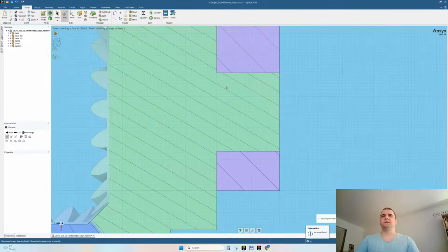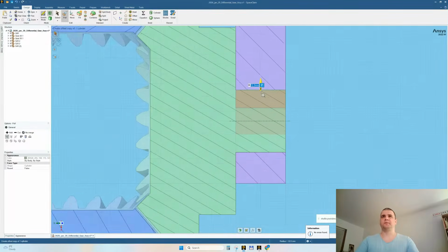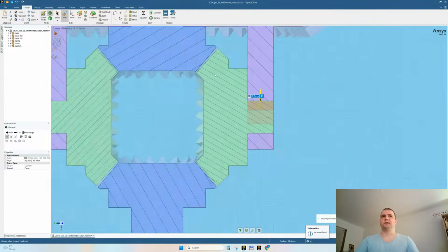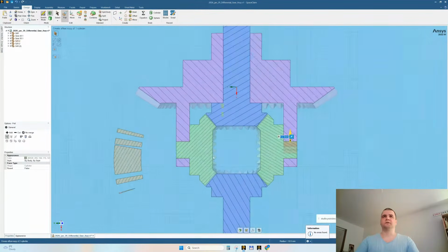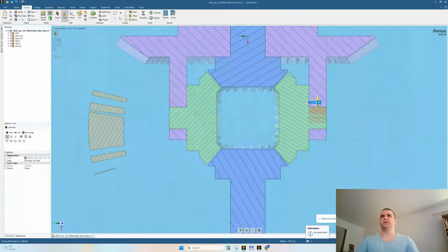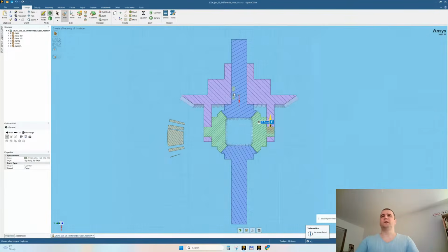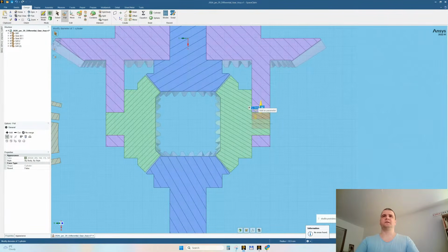So I need to take into account the fact that it's perfectly touching. There is no gap. I need to take this into account. Also here, the shaft is perfectly touching with the hole. Pardon my English. And let's go with these because my intention is to create joint boundary conditions, Revolute joints. Yes, this is why I don't care if it has gaps or not.